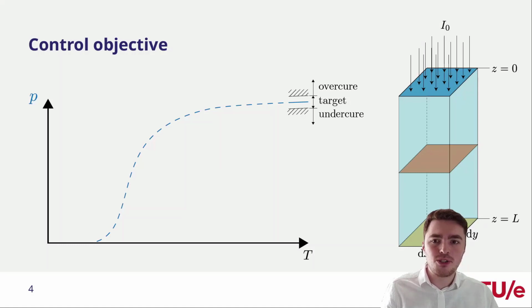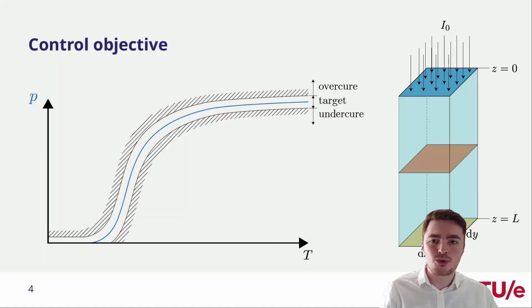In our proposed approach, the actuator intensity is modulated and the curing degree is measured by means of spectrometry. This provides the means to control the temporal evolution of the curing process throughout the layer, which in turn will yield better and more consistent end products.